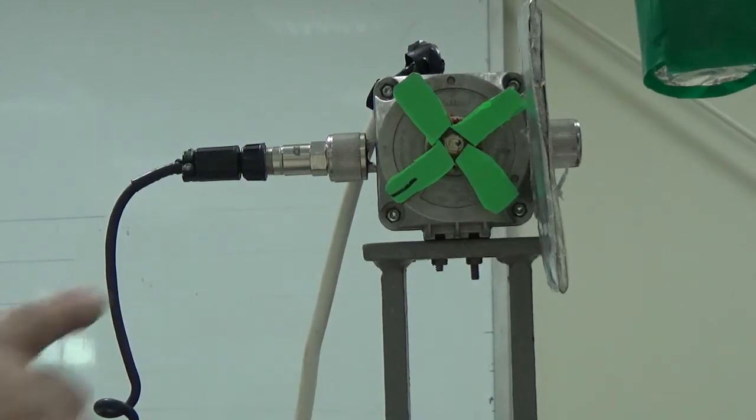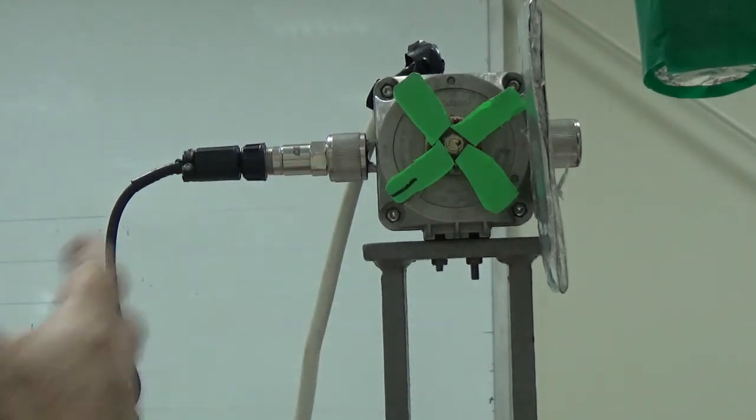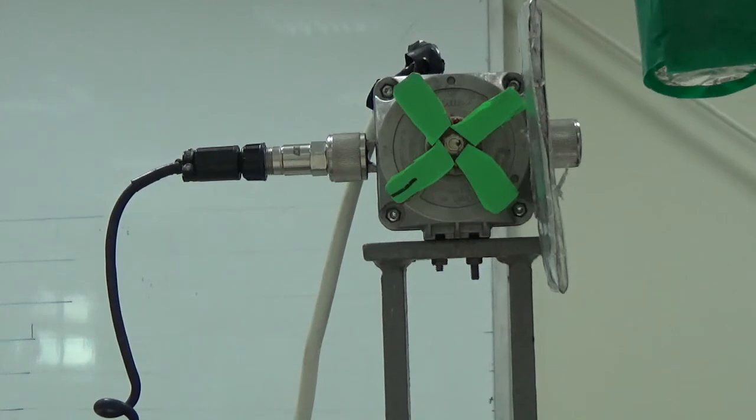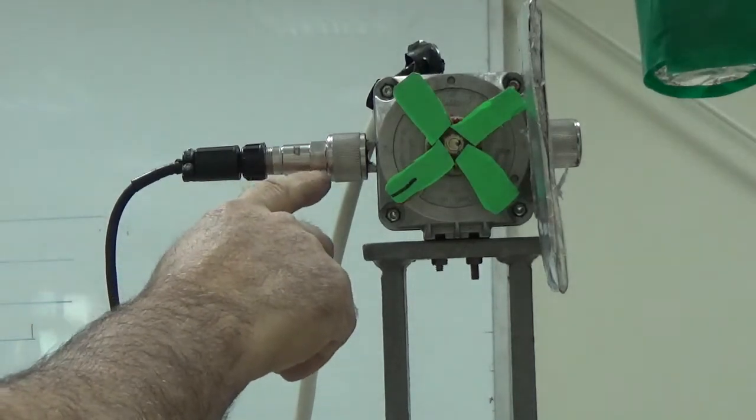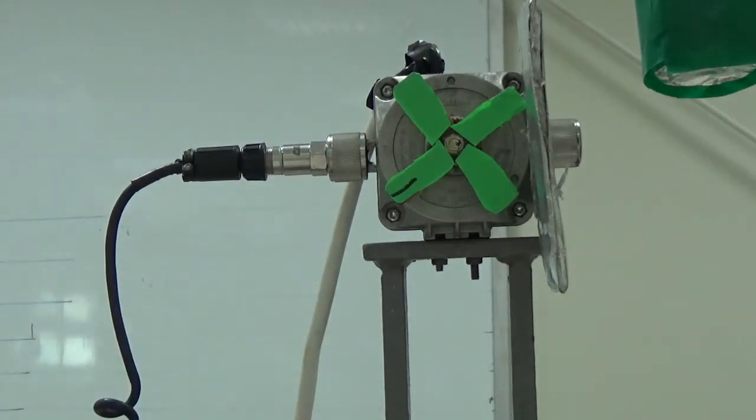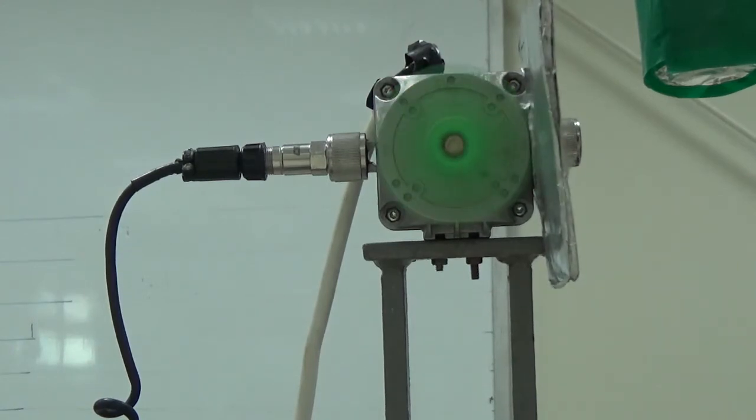This is a sensor, an accelerometer. When there is a vibration in this fan machine, a charge is produced in this accelerometer, and that charge is converted into voltage, and from that voltage we can get vibration in acceleration, velocity and displacement. So let us start this fan, and then we will see the spectrum and waveform.